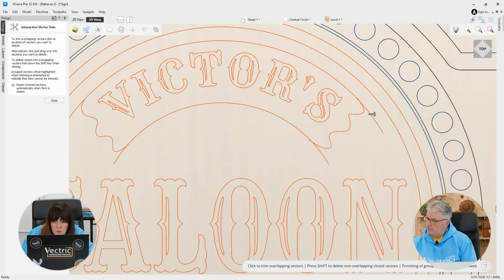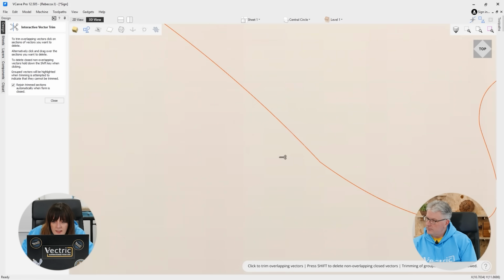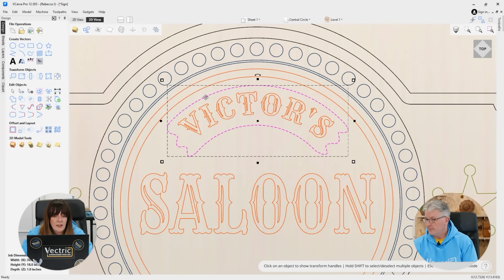And then we'll go into our trim tool, and we'll just take that. The trim tool is great for this sort of thing, yeah. And as you showed earlier, if you hold in your button while you're moving the trim tool, it'll actually cut all the lines it runs into. Yeah, absolutely. And quite often I'll run into this problem where I'll forget to tick off the little box where it says join up your vectors when you've trimmed them. So there's a little option there to make sure you have that clicked if you do want to join those up. Yeah, definitely.